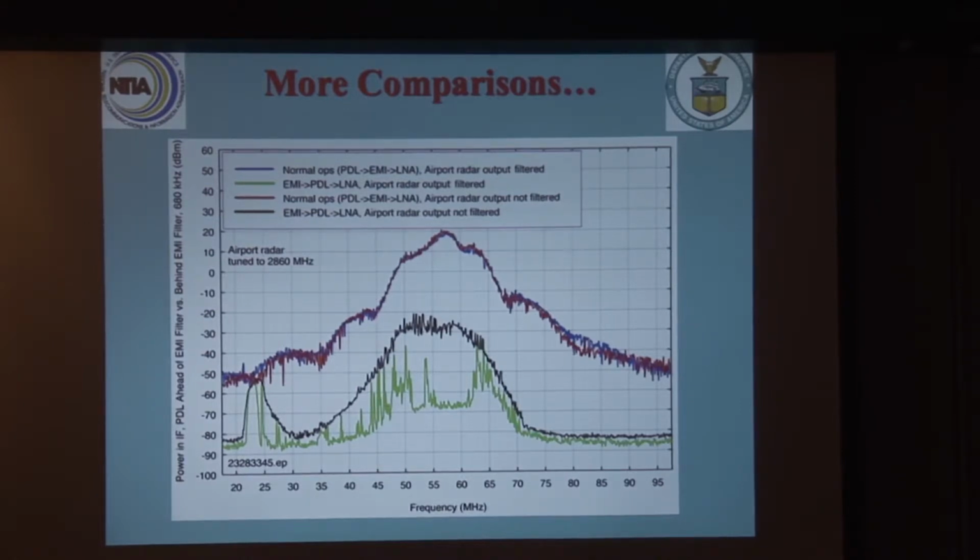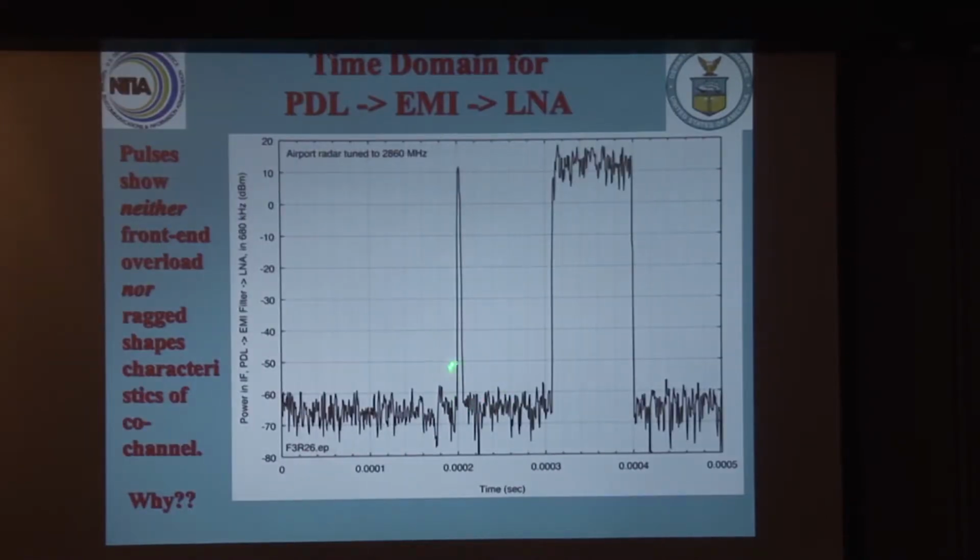So we did stop both the rotations, and we physically moved the antennas by hand until they were lined up on each other. We could have done this with the two antennas rotating, but it would have been much, much, much slower as a process, and therefore would have made the whole problem much more expensive to solve. Like on the last slide where you showed the pulse shape, we would have had to wait a long time to try and look at the interference. Because we'd be looking for either main beam to main beam coupling, which would occur rarely, or at least main beam on the weather radar into the side lobes of the air traffic control radar, which would occur about every 30 to 60 seconds, which is still awfully slow. Right, exactly. So we went ahead and bore-sighted them. Good point.